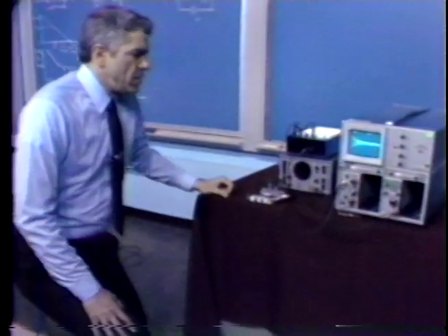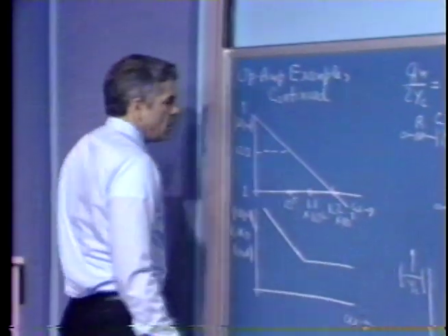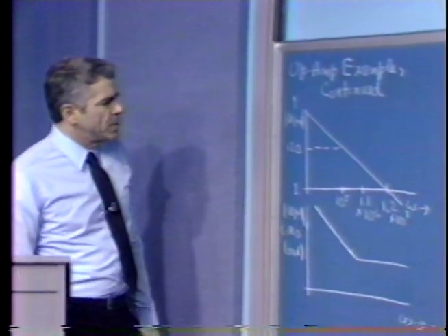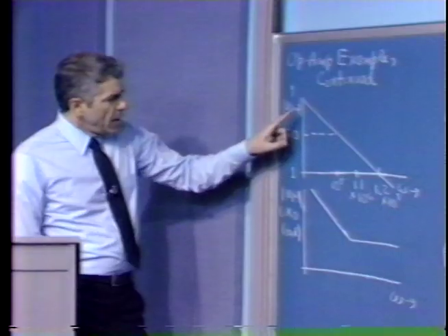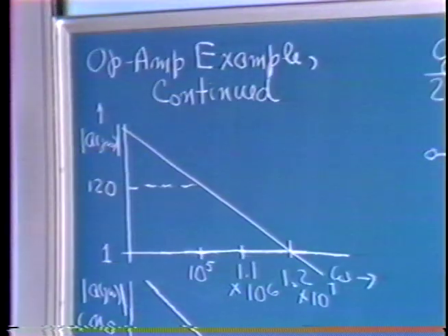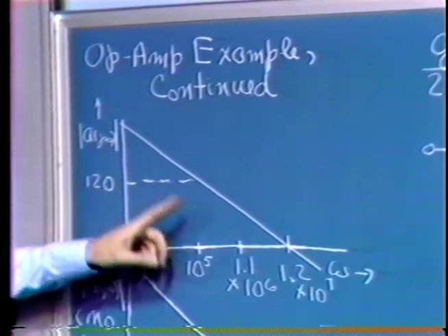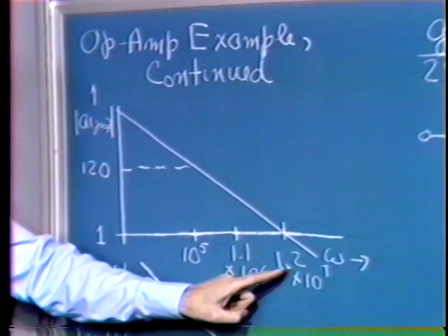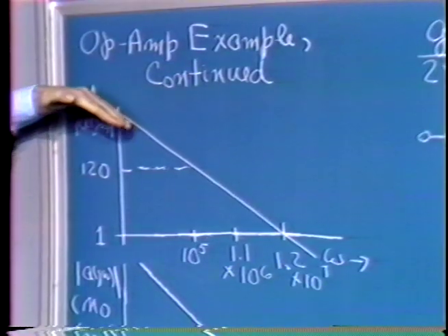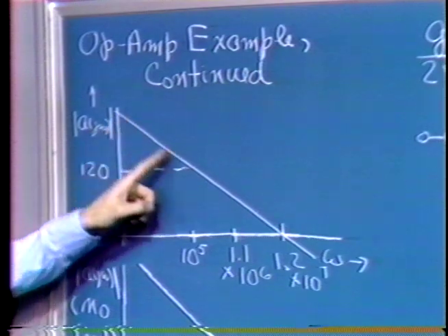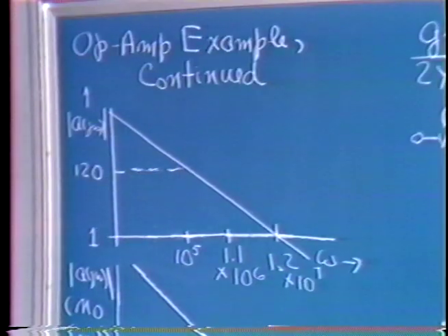We can explain why that happens. Let's look at the amplifier open loop transfer function in the absence of a capacitive load. Here we have chosen single pole compensation. For this particular amplifier, with the 20 picofarad compensating capacitor that we're using, crossover occurs at about 2 megahertz, or 1.2 times 10 to the 7th radians per second. So this is the open loop transfer function of the amplifier, a single pole roll-off over a wide range of frequencies when we have no capacitive load.